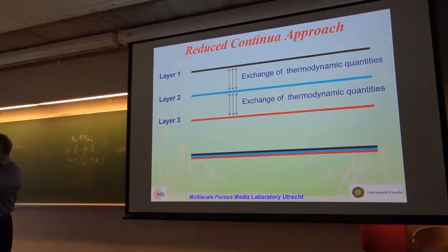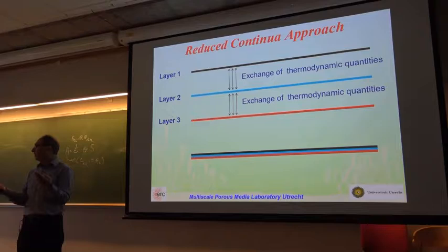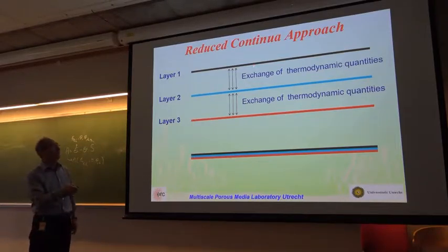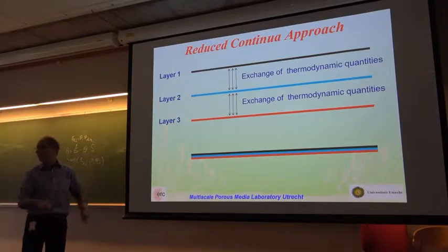Well, I mean, take for instance the exchange layer to be air, and the black, blue, and red layers to be a metal foil. Then the conductivity of the material in the direction normal to the surfaces is 0, whereas along the surface it is the conductivity of the metal layers. Correct. So you cannot take this air out without changing the properties of the system. I change the property of the system, but I don't model the air explicitly. The way I model the air is that there is a heat exchange, and for that matter mass exchange, between these layers. And that exchange is a function of what is in here.